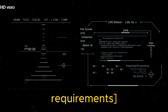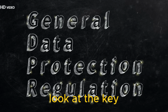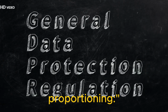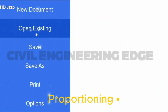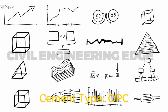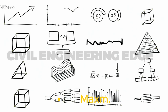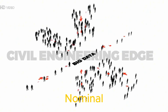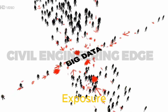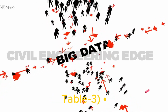Before we start, let's look at the key data required for mix proportioning. Stipulation for proportioning. Grade of concrete, M20. Cement type, OPC, ordinary Portland cement. Max nominal aggregate size, 20 millimeters. Exposure condition, mild, IS 456 Table 4. Minimum cement, 300 kilograms per cubic meter, IS 456 Table 5.